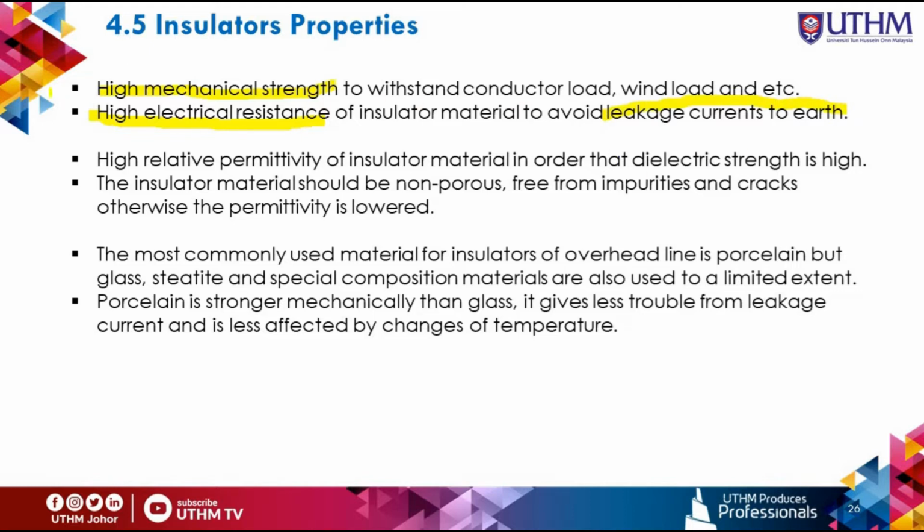And then high relative permittivity. What is permittivity? It is the ability of a material to store energy in an electric field. So the insulator must have a high relative permittivity in order that the dielectric strength is high.